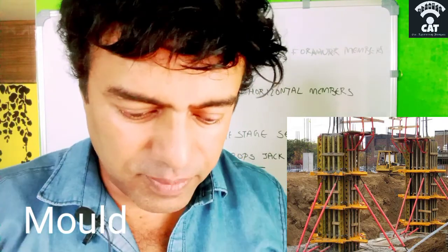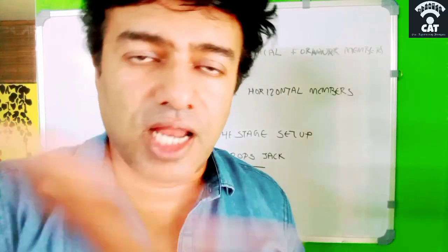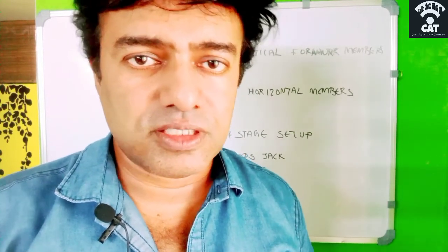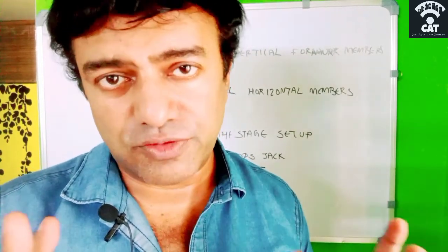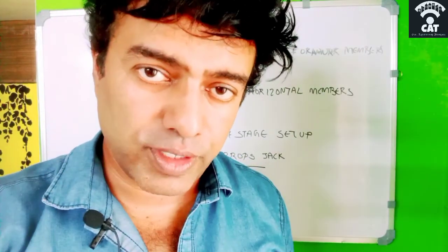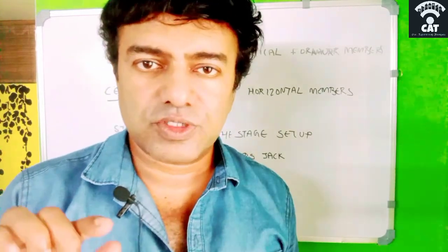So first we make the mold. Mainly we are using plywood for that, and in slabs we are using metal sheets too. So take the case of plywood. Plywood will act as a formwork which will make the shape first, and then we pour the concrete into it, and then we attain that shape. So this is called formwork.